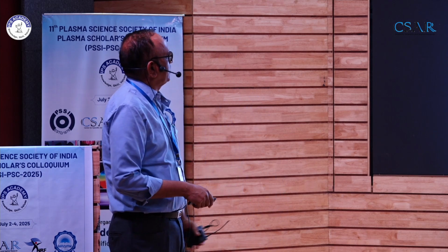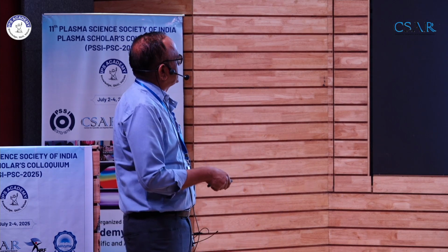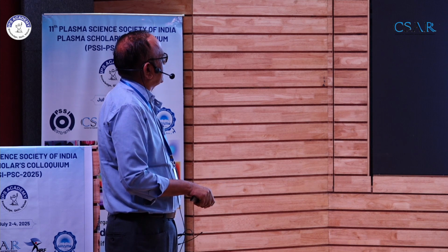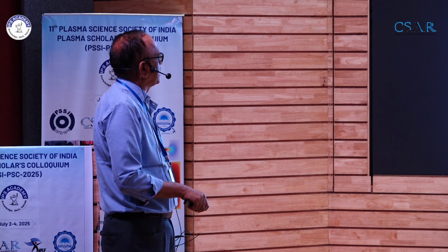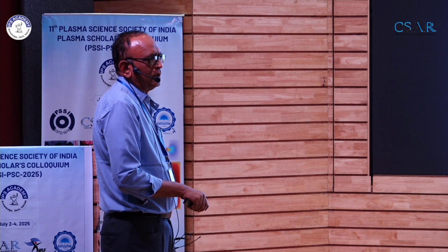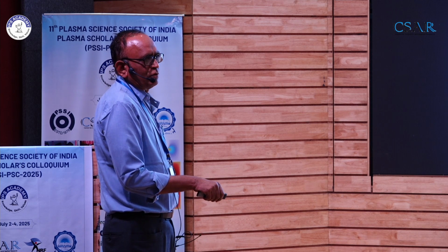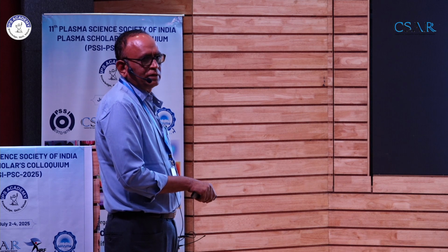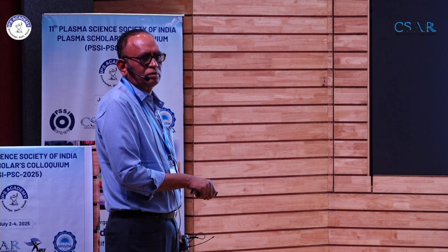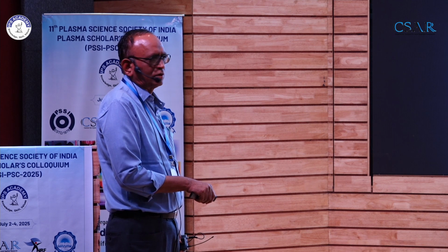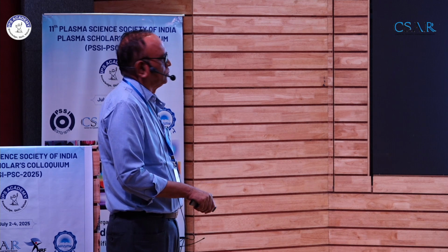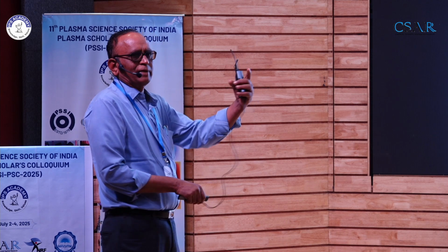So there is a scheme where, in the chamber, I have magnetic coils surrounding this stainless steel chamber, which means there is an axial magnetic field. And then from the microwave hardware, I am transmitting these microwaves through the waveguide. I am getting it converted from rectangular mode TE10 to TM01, circular symmetric mode, and that plane polarized microwave radiation is launched into this chamber. Now there is an axial magnetic field.